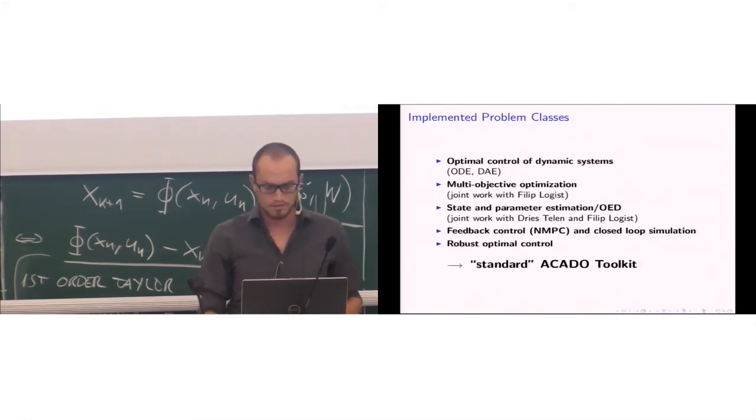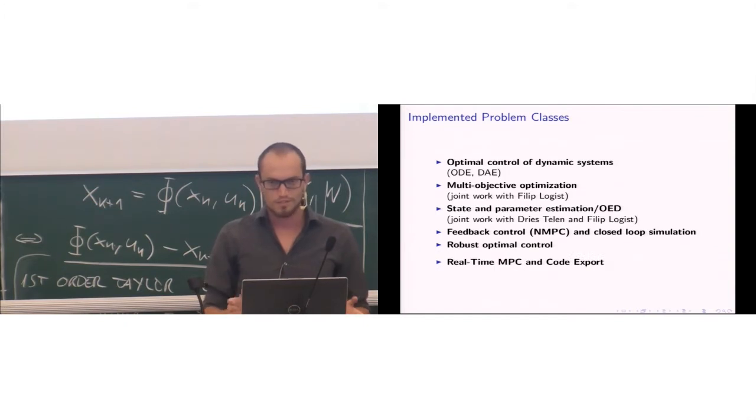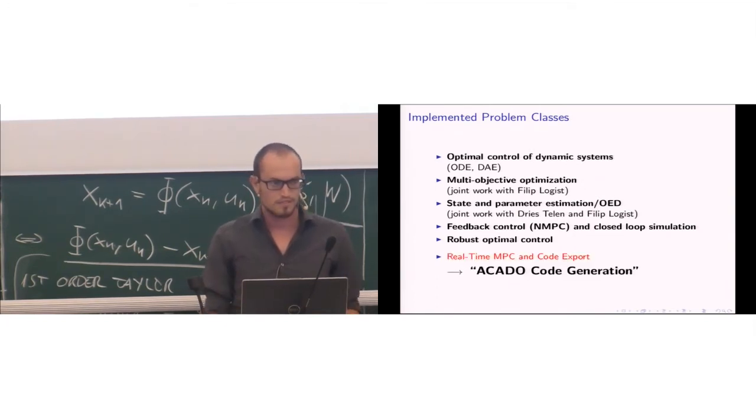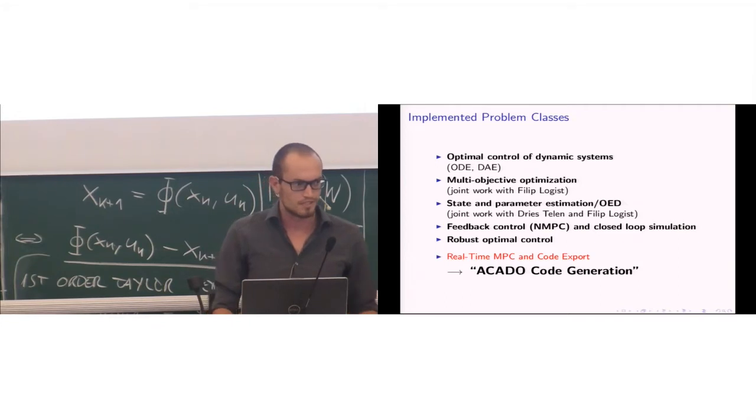So this is what I will, in this talk, call standard ACADO, because the idea is that the solvers are written in C++ in a generic way. You can definitely use them today, they're still there, but they're not designed to be directly used on your embedded system. And as our course has the word embedded optimization in it, it's not what I want to talk about now. What we want to talk about now is real-time MPC and embedded applications using code generation. That's why my title was ACADO Code Generation and not just ACADO Toolkit.